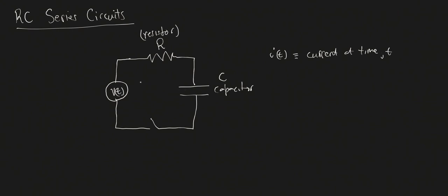Now, in an RC circuit, the way capacitors function, and in fact, I'll very briefly say the reason why you would have components like inductors and capacitors is that they give you a way of storing energy. But the way they store energy is different. An inductor with the coils will store energy magnetically, in an electromagnetic field, whereas a capacitor will store it electrostatically. So you talk about getting a charge on your capacitor.